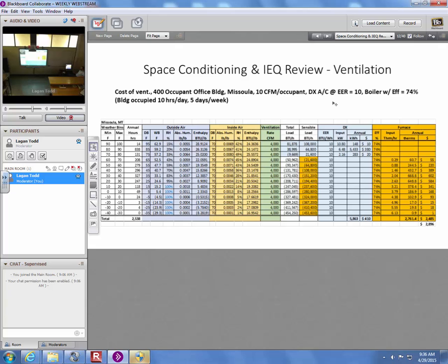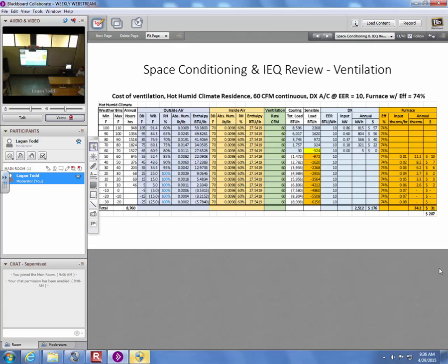So now the point I want to make here is that in this course, again, we focus on residential buildings. So somebody might say, well, $200 a year, it's not that big a deal. It's not a ton of money. Somebody else might say, well, actually, I could really use another $200 a year in my pocket. That seems like a pretty efficient building, isn't it? Again, just the ventilation. That's not your total building energy. Just ventilation, 60 CFM, just what the bathroom fan is pulling in. That's quite a bit.